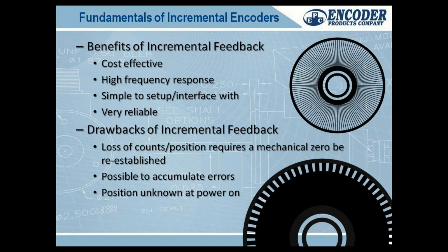Absolute encoders and fancier encoders, if you will, that have serial outputs, CANopen, SSI, Profibus, whatever, they're going to have much slower response time, generally in milliseconds. And it's because you have a back and forth talking that needs to happen and checking packets and all this. So you will never get the frequency response from a serial encoder or an absolute encoder that you get from an incremental encoder.